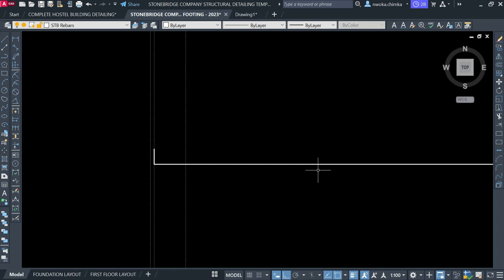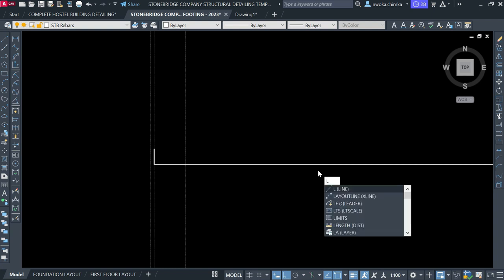not be too expensive, because if you use more lap length, that means your building cost will be very, very high during construction. So I'll just keep myself within what the code says, 50 times D as my lap length.